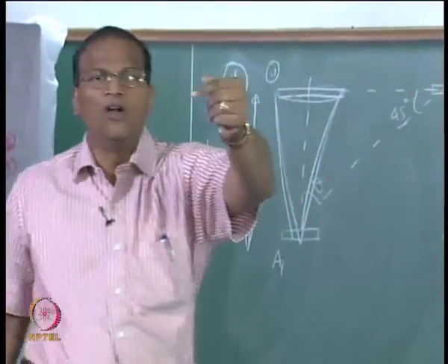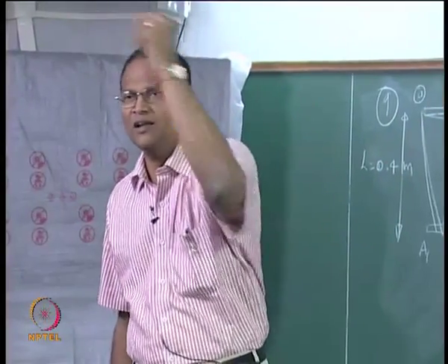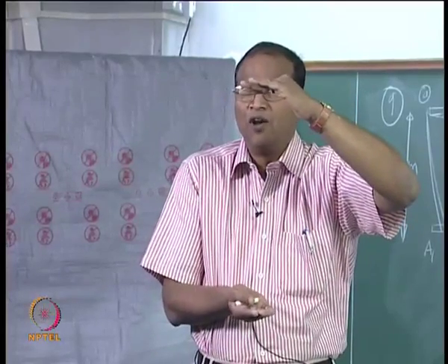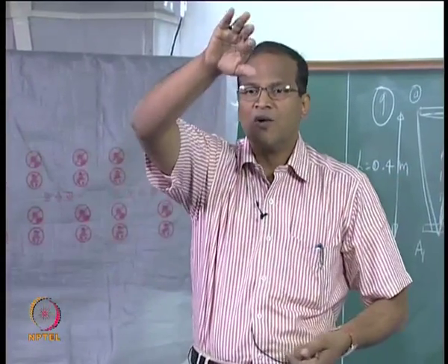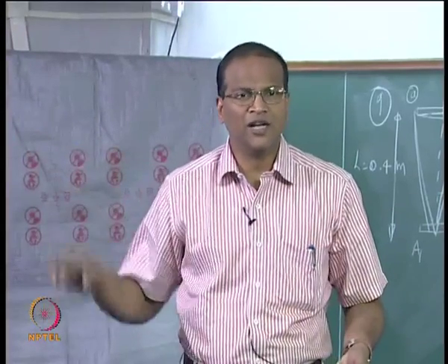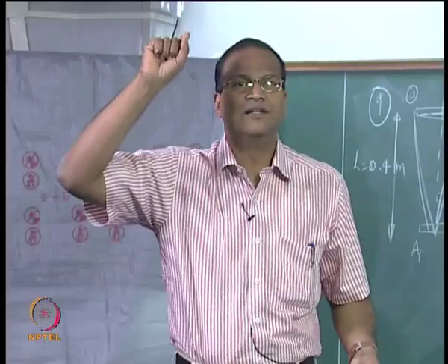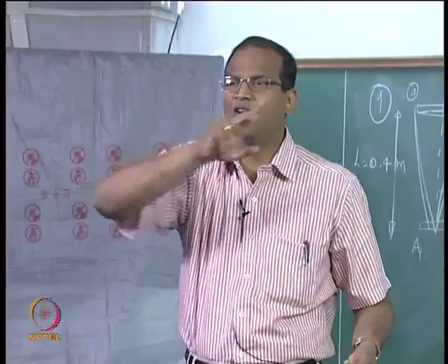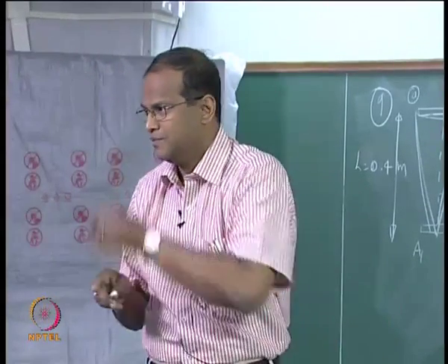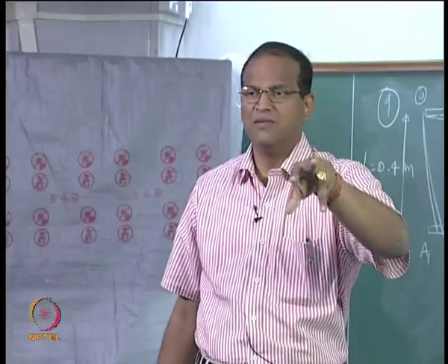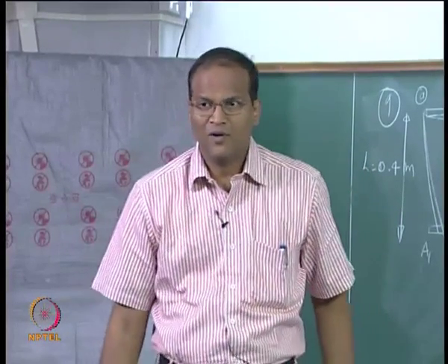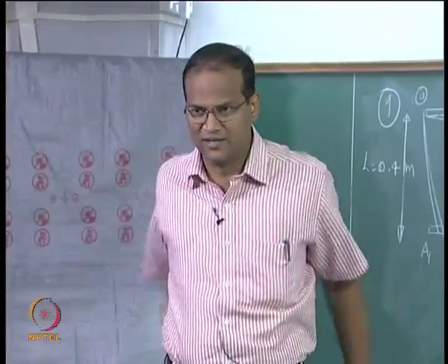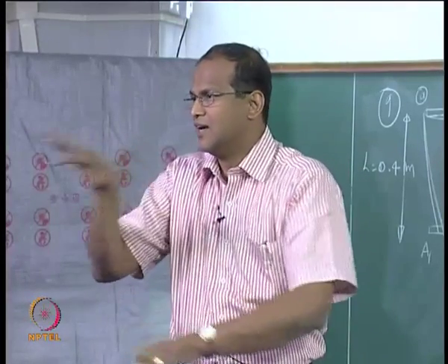Now the more difficult part is that this detector is now moved horizontally, so that cos 0 is no longer cos 0, it is cos theta now, and this distance 0.4 meter is also changed because now it is at an angle. Because the distance is also increased, expectedly the radiant power intercepted by A2 has to go down. If I had given a value greater than this, straight away you could say the problem itself is wrong. Now from 10 to the power of minus 6 it became 10 to the power of minus 7. That does not mean emissivity is exponentially going down, because other factors are not helping it receive more radiation, like the radius has increased and the angle is also changed from 0.